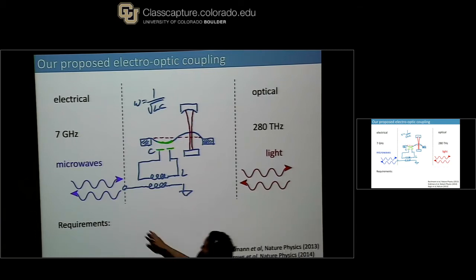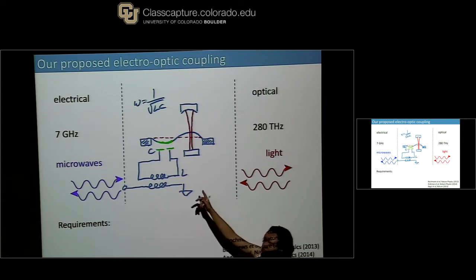Yeah, so the electrical circuit is connected to a transmission line that's over here, and it's inductively coupled through those two inductors. Yeah, so the top part, that's just floating, and if you sort of bend that image, you can think of it as two capacitors in series. So it's a tricky way of allowing us to just have that top part not electrically connected.